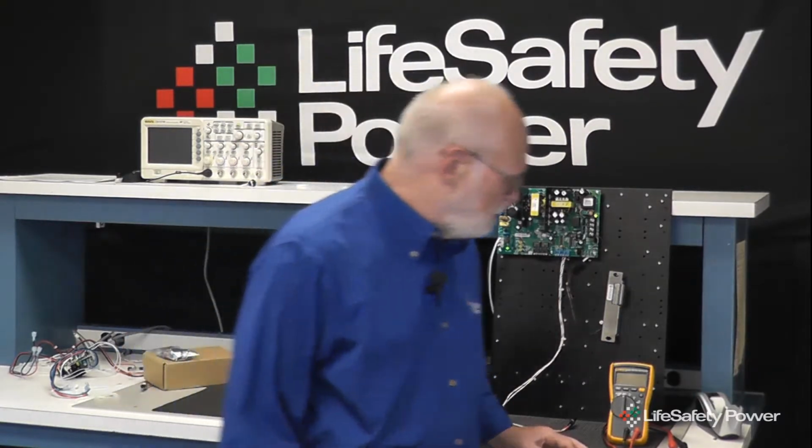When we use the FPO alone, we're using the fire alarm interface circuit built within the FPO. I can connect a switch contact directly to the FAI, and when I activate that switch contact, it will control the DC2 output in order to control the lock directly.